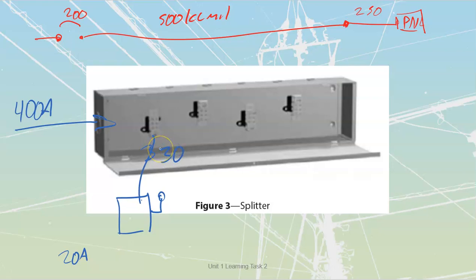write that right next to that one there. I'm allowed to use 30 amp wire and run that down from here. As long as my switch is 30 amps, I can use the 30 amp wire. It's rated to that. I just have to keep this thing underneath 3 meters long. Really handy. We then do have inside of this overcurrent device, it's a switch. It talks about switchboards, panel boards, and control devices. Inside of here is then where I would place my next set of fuses that would then protect the rest of the conductor going out to whatever it is. Maybe it's a rooftop unit or something like that.